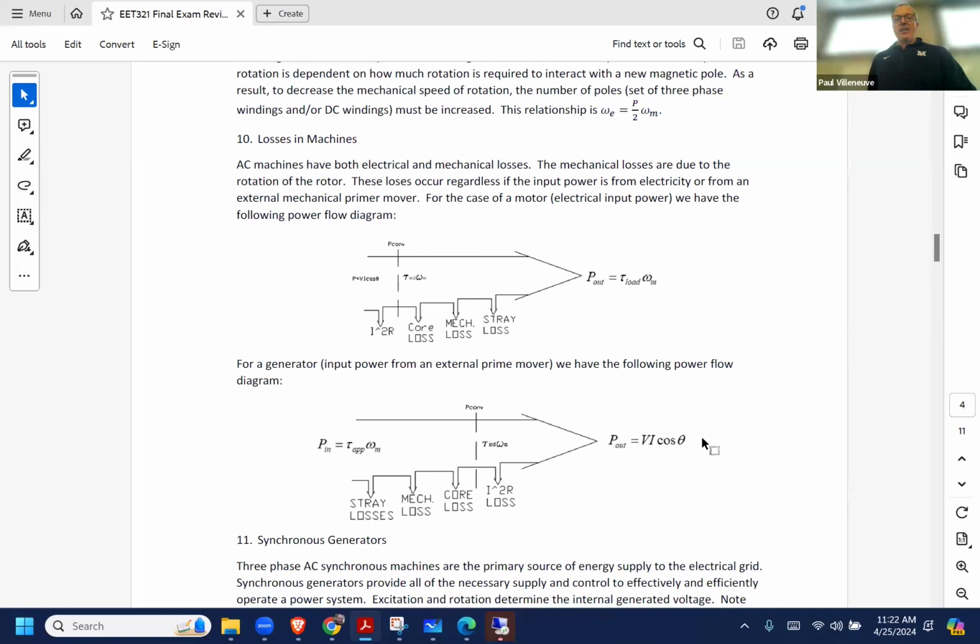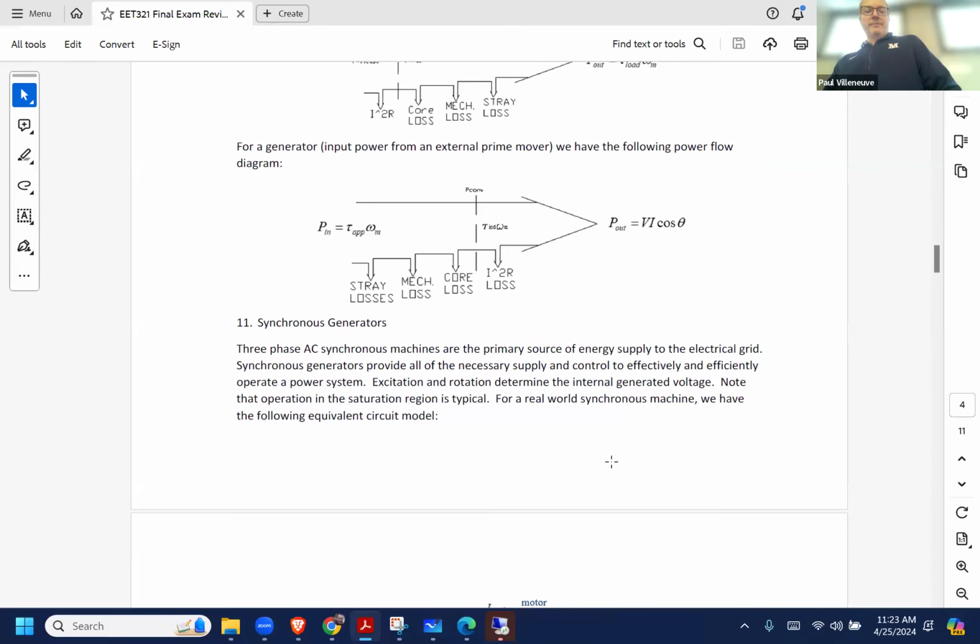And then this power here is induced. That's why you can see there's a torque that's here, because if you didn't get any electrical power out, that would give you an induced torque. The unit would continue to spin up. It would speed up and speed up and speed up until it got damaged. But the electrical power out is giving us an equivalent or an induced torque.